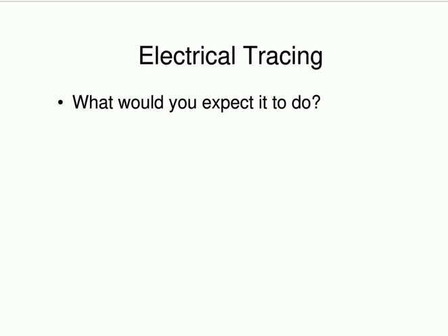Electrical tracing. What do you think is happening when we talk about electrical tracing? Could be, depending on the product, yes. It's a good point. I'm just reading the messages coming through from those watching on YouTube. Electrical tracing, how do you think it works? So we know, with steam tracing, or if you've got a hot liquid, you just pump it through a small pipe and you put some insulation around the pipe, and so you induce heat into the pipeline. What would you do for electrical tracing? Any ideas? I'm just waiting for you guys to hit the keyboard.